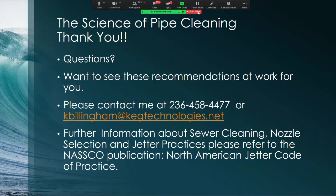Okay. There's another one just popped up here. Is it ever advised to use the truck vac downstream of the manhole to create a negative pressure to assist in airflow, i.e. avoid blowing toilets? Most trucks are moving 4,000 to 7,000 CFM. Yeah, the trucks do move a fair amount of air. The way I heard the question is downstream from the hole you're working in. So that is, in effect, going to increase the airflow moving down through the pipe. So I think that's going to have a negative effect.